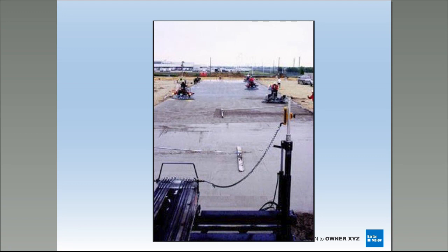This is an example, again, like I said, a good example of, you can see the laser screed. That's the front end. He's running the placement. You're following it with a nice long channel float, so that's going to help you out with your flatness. Then they're coming in and doing an early break and running the check rod, all right? So that tells me they're going for a high F number, right? And then you're following up with your machines. Must be setting a little bit fast on them because the machines are awful close to that check rod.